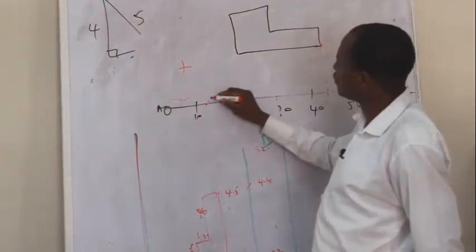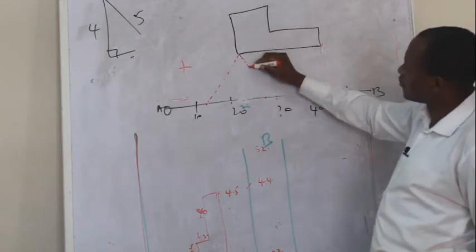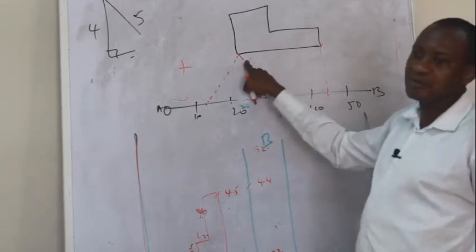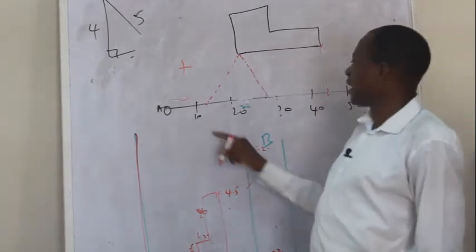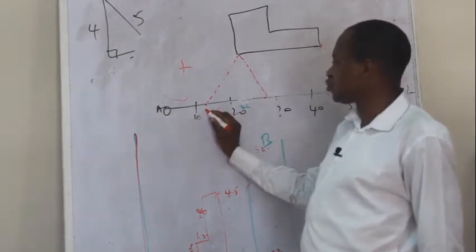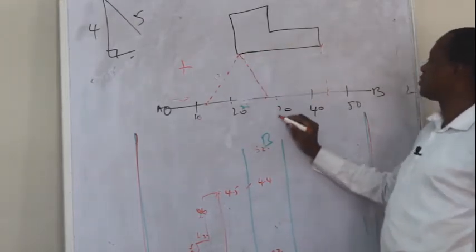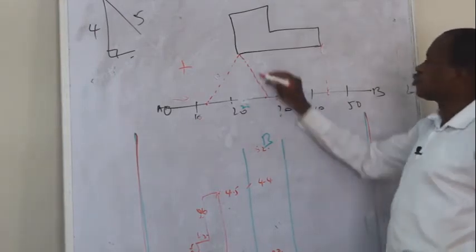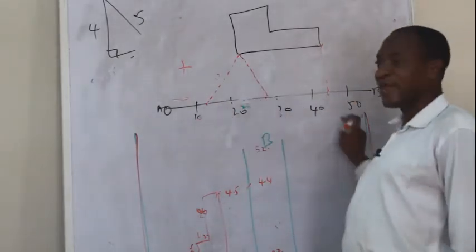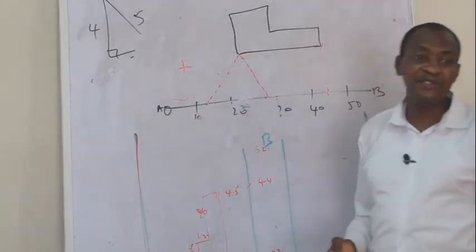At this point, I can measure to this point, and at another point here, I can take another measurement to this point. So if I measure like this, this is what we call tie lines. You will notice that at 12, maybe around 12, I take measurement, and I take this measurement to this place, maybe 15 meters. At 28, another one to the same point. So when you take such measurements that are not perpendicular from the line to your detail, such measurements are called ties.